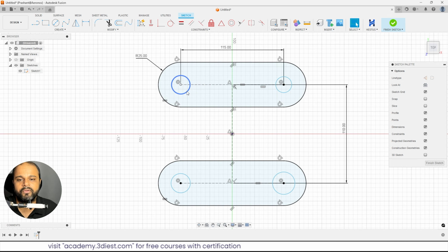So these hooks are very simple. So let's first plan where we'll create the sketch for these hooks. We'll go back to our Fusion 360 design, and this time we'll be creating a sketch for the hooks onto this face, that is exactly at the center of this cylindrical body. Here you can see that. Now what we'll do, we'll activate the create sketch tool, and then I will select that face to create the sketch onto that face. Now the tool is active.